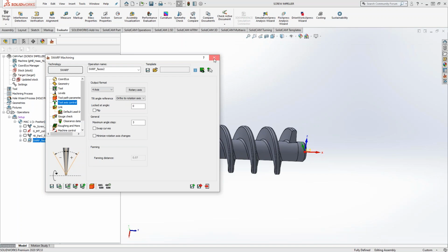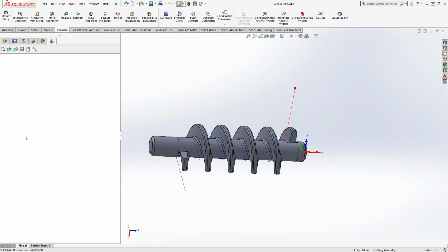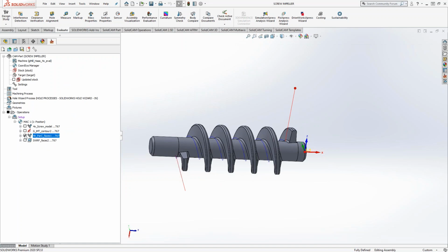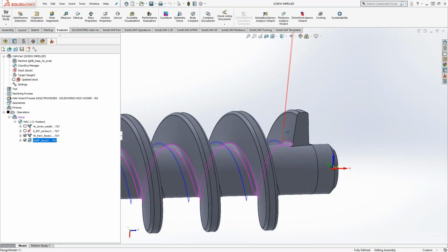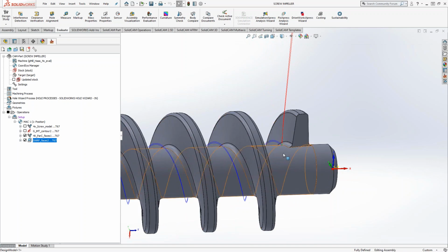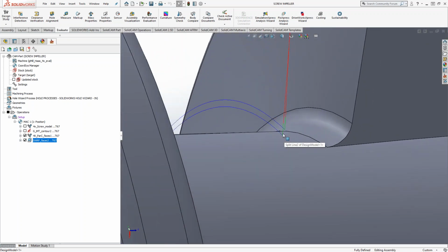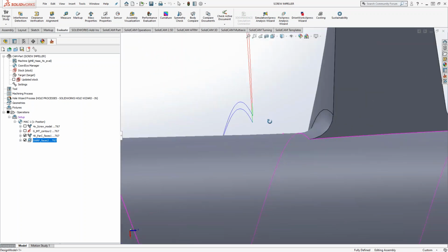Whereas with the simultaneous 5-axis toolpath, I could still do the same thing. I just had to modify the parameters to do those specific things I'm looking for. But if you look at the two toolpaths together, they are virtually identical. The only difference is one is probably dipping a little lower because there is a corner radius on my tool.